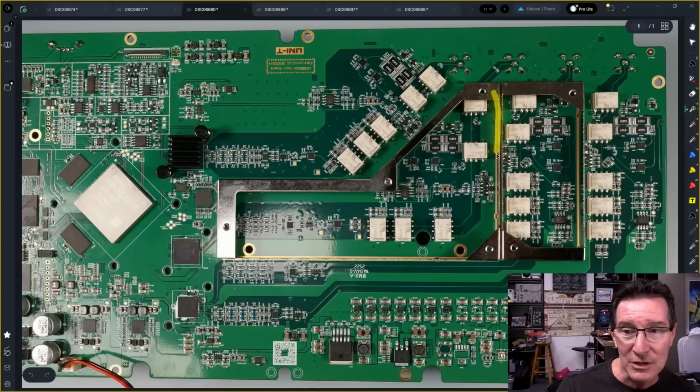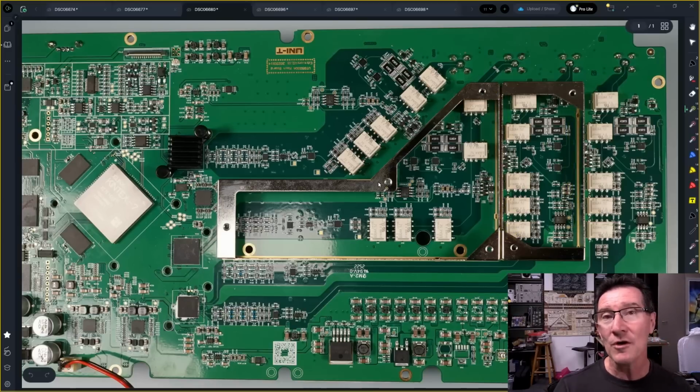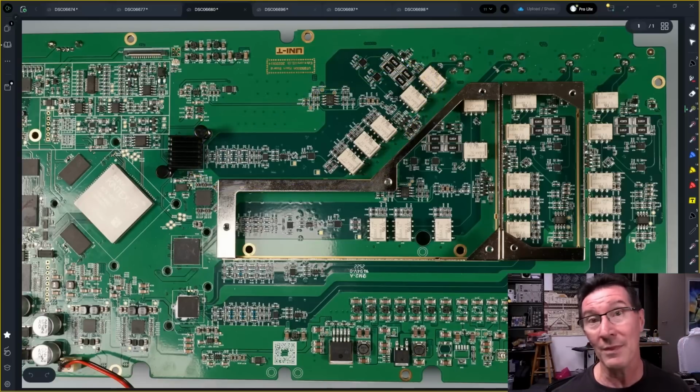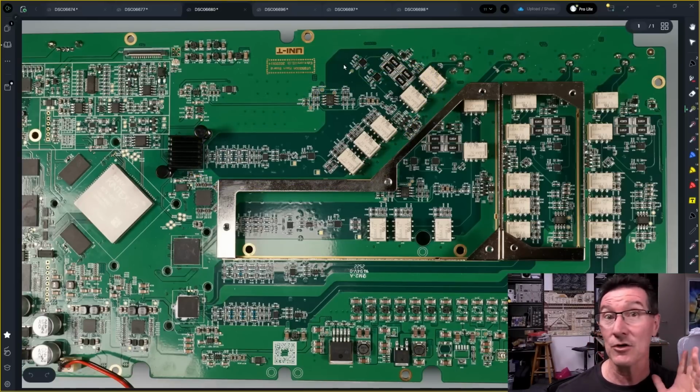For these shieldings, you can see the copper being left off. So they actually knew from the get-go that this was just about coupling between channels. So it's not like they built this and then tested it and go, oh, we can leave off this shielding. They knew that from the get-go when they designed the PCB. So definite cost cutting there.